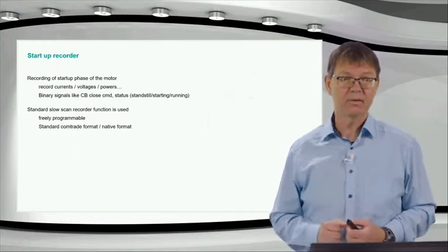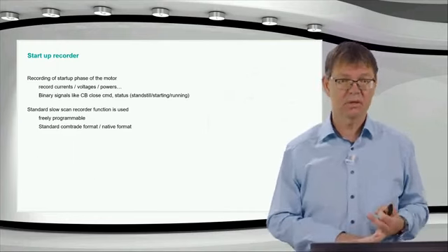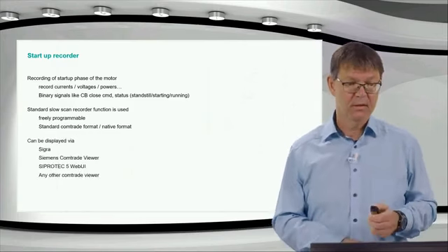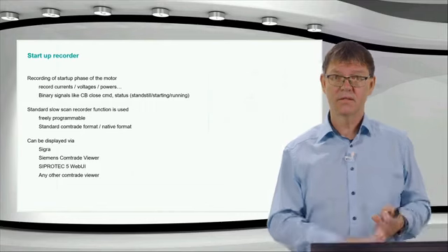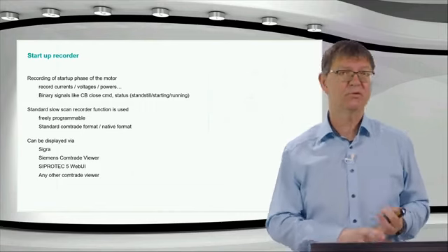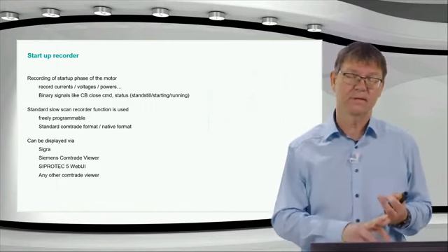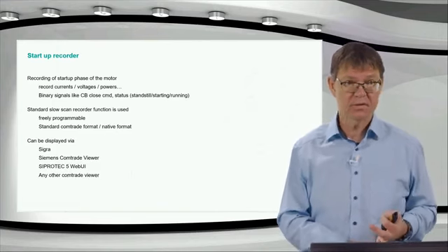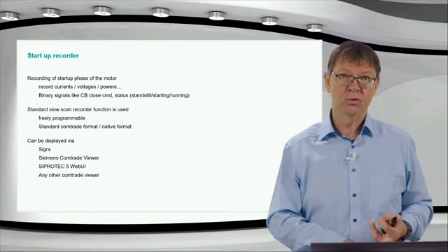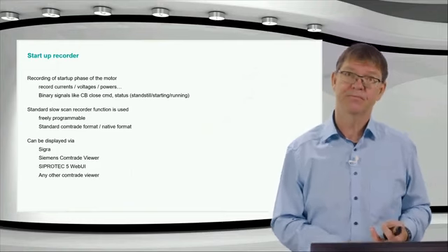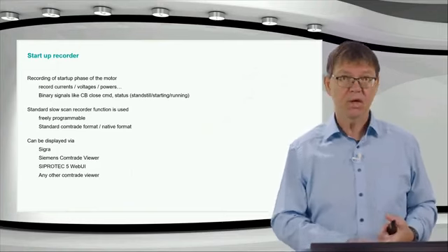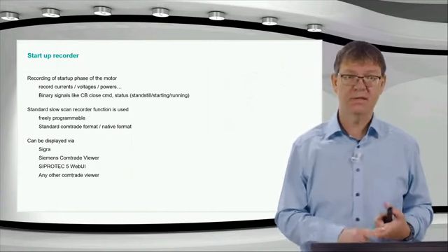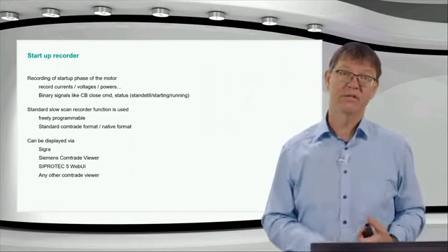It's freely programmable, and it's a standard COMTRADE format or also a native format. And therefore you can view it with SIGRA, the special tool belonging to DIGSI, to show and analyze fault records, the Siemens COMTRADE viewer, but also with our web UI, the web user interface, which is built into the relays, or any other COMTRADE viewer.